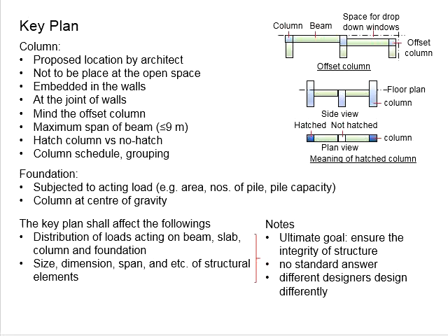When you have sufficient soil bearing capacity, depending on your design, you can use the footing. You need to provide sufficient area of the footing so that the soil is not overstressed, and you can take full advantage of the soil bearing capacity to support the slab which is in contact with the ground.